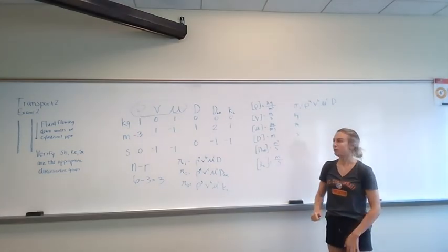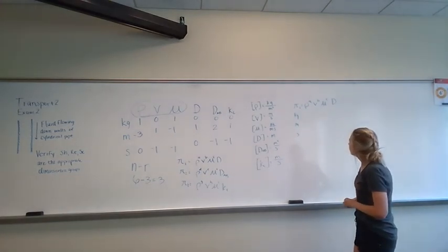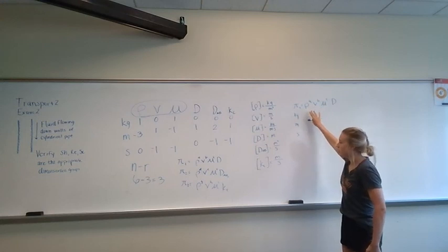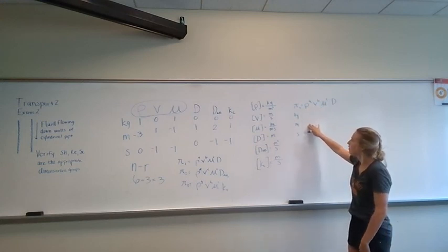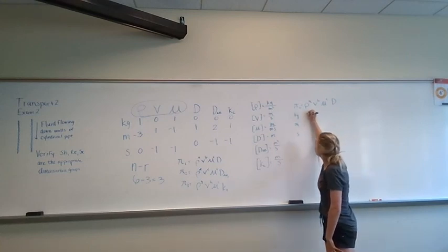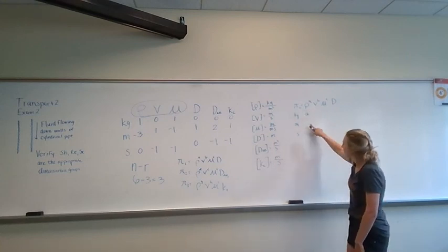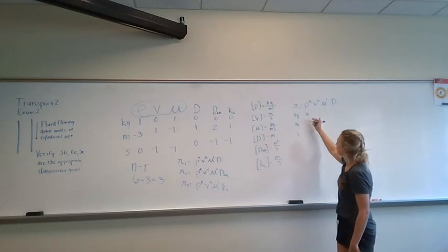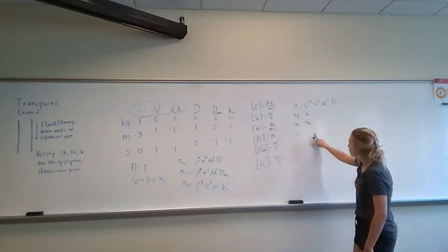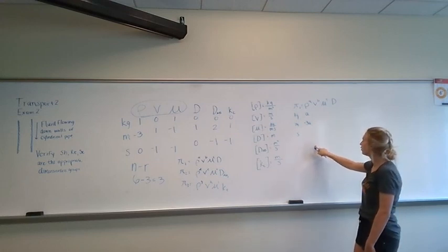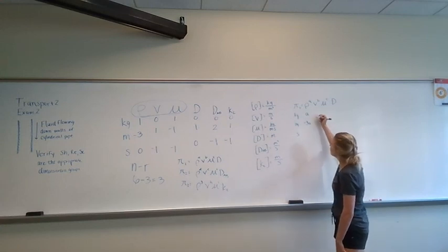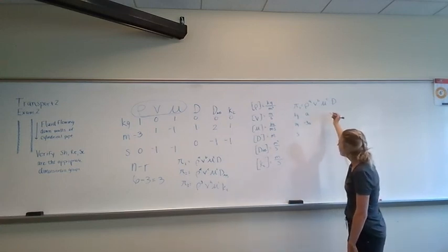each of these parameters. So, for example, for density to the A power, density is in terms of kilograms per cubic meter. So kilograms, we'll have kilograms to the first, so we'll put an A there, and then meters to the -3, so we'll put a -3A here, and then no seconds, so there will not be an A term for the seconds equation. And then moving on to velocity, no kilograms.